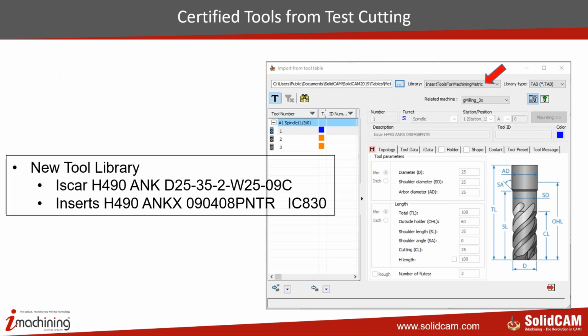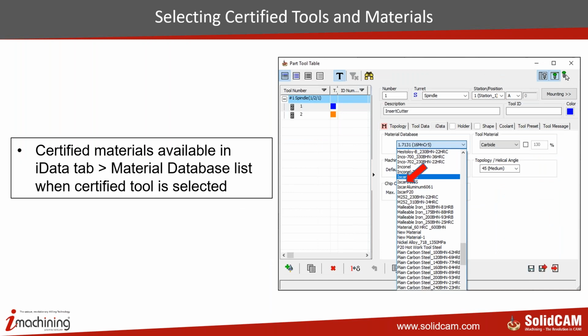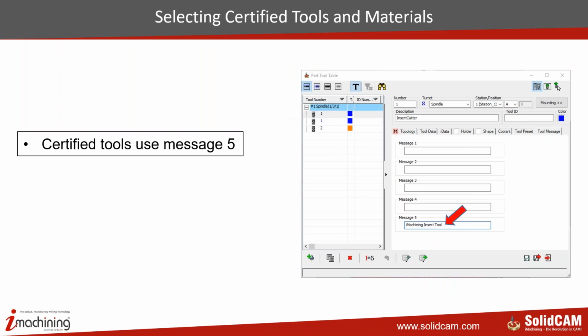We also created a new tool table for the certified ISCAR tool that can be imported. We have added the tool table to the install. With the certified tools selected, the certified insert materials will be shown and will be able to be selected in the iData page of the tool table. We used message field 5 with the string iMachining insert tool to enable the selection of insert material databases. If creating your own tool and material combination, adding this string is required.